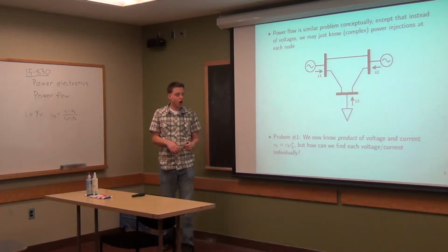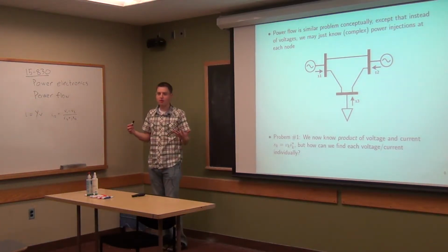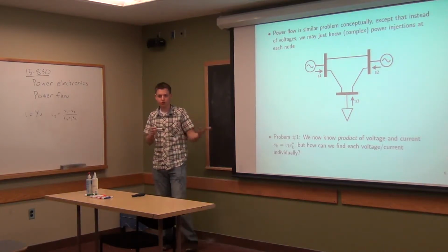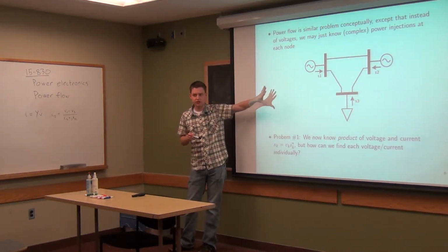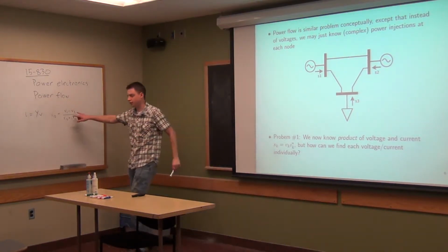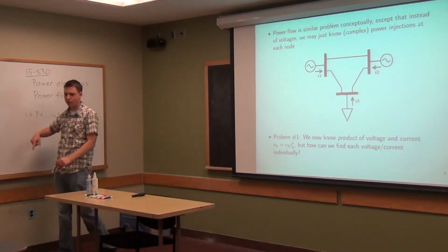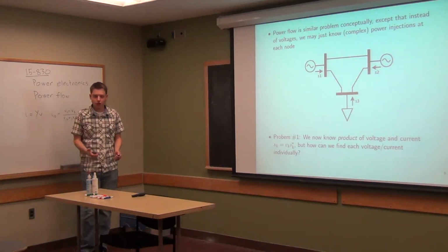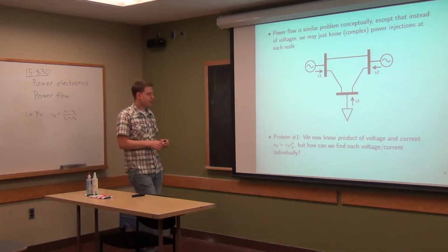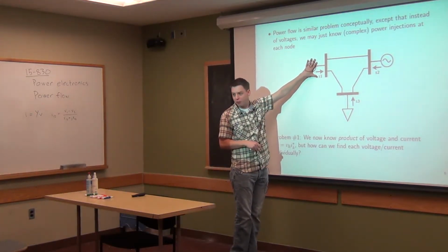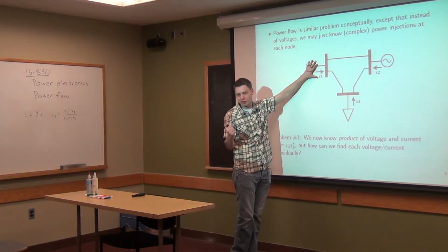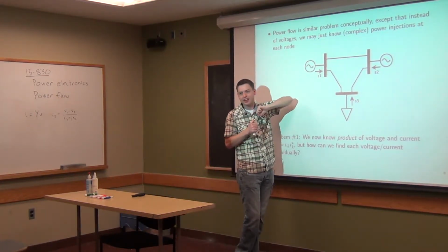But what we know, informally speaking, is much more like we know power. We don't know what voltage or current is in this setting. And so now we just know the product of these two things, and the equations become much harder to solve. In a second, I'm going to get to the fact that we actually don't know reactive power for generators. We know their voltage magnitude, and we know their real power, which is a little bit different. I'll get to that in a second.